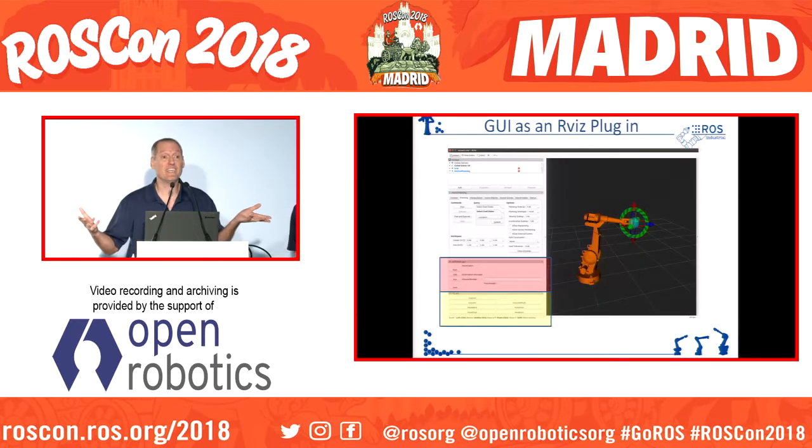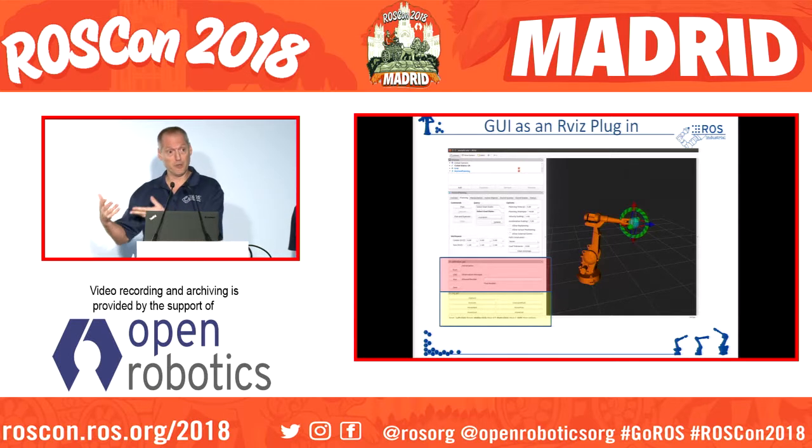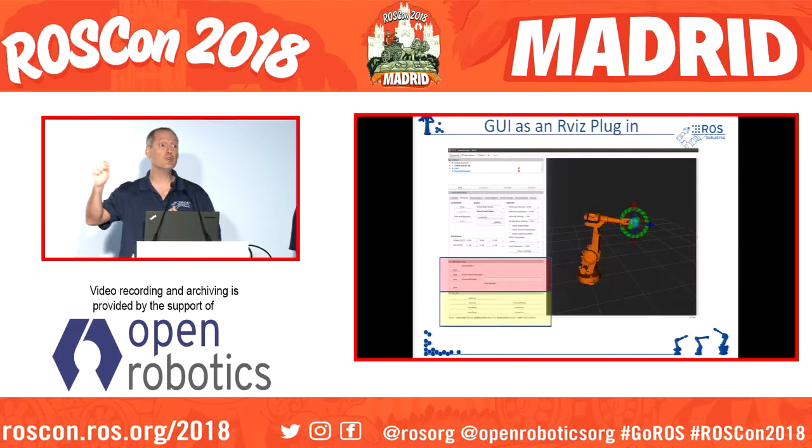So to make it even easier, we've now added GUIs in that same GUI that I talked about before in RViz, where you can just click on the buttons and have it say, take a new observation. So now you can use MoveIt to move the robot around, and then just click, oh, take another picture right here, this is a good one. You can then display your images, and it will show you that you've got a good observation, and then you can finally run it and save the results, and it will move the transforms around, and everything's good.